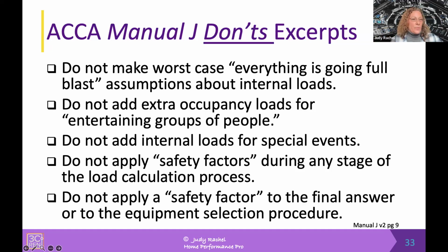Don't add internal loads for special events, same kind of reason. Don't apply safety factors during any stage of the calculation process, and don't apply a safety factor to the final answer or to the equipment selection process. Believe me, you're not going to come up with an undersized load to be sizing your equipment on if you go through the procedures appropriately.